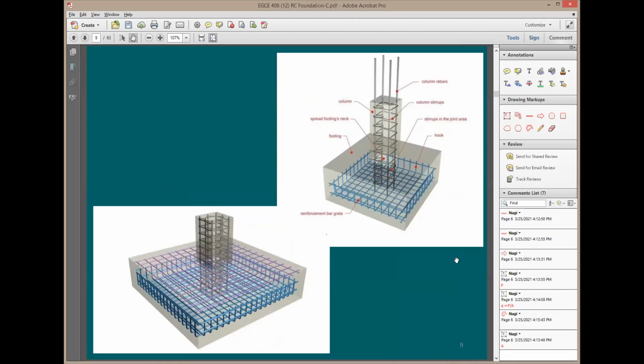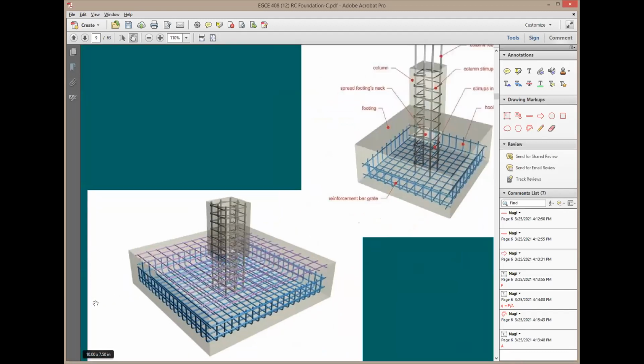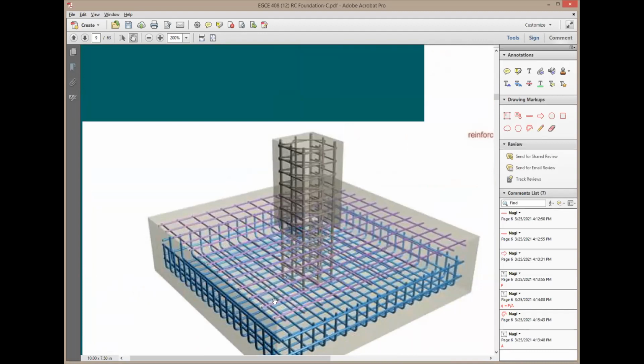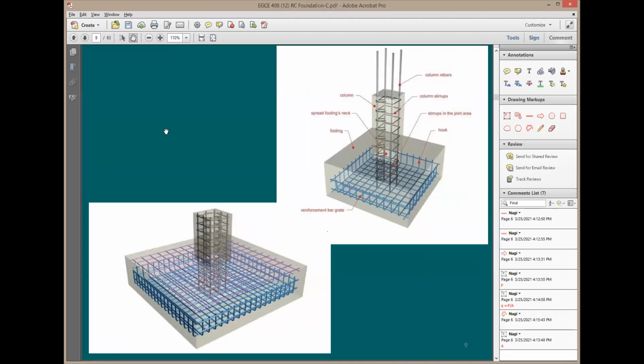Another footing, very similar to the one before it. Exactly the same design. And now all of a sudden, I see here a new mesh. We call this mesh. You see, I have a bottom mesh and it has hooks. At each end, you have a hook. But all of a sudden here, I'm adding top reinforcement. And I'm thinking here, why would I need top reinforcing if I just stated a minute ago that all the rebars on the bottom are going to be in tension? It means the top is in compression. Why would I need any top rebars? I'm going to be talking about this in a minute.